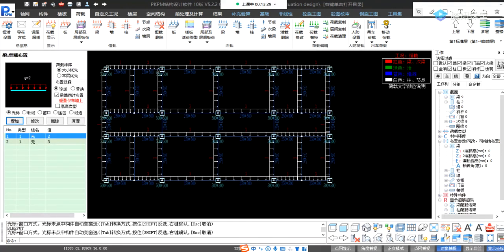You can see here the beams. If there is a wall, there must be a beam node along the beam. And we can calculate the exact value by calculating the wall. This node will also belong to the dead load because it's the self weight of the walls, and we can check the self weight of the wall. Then we change it to a linear load.